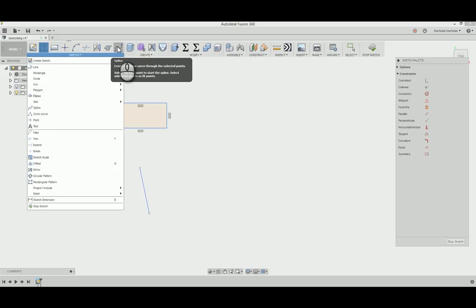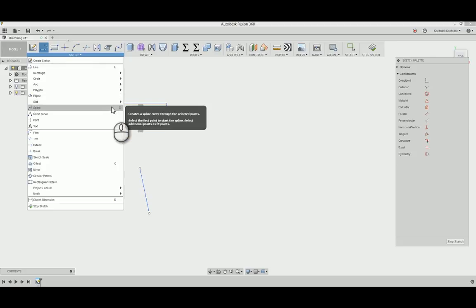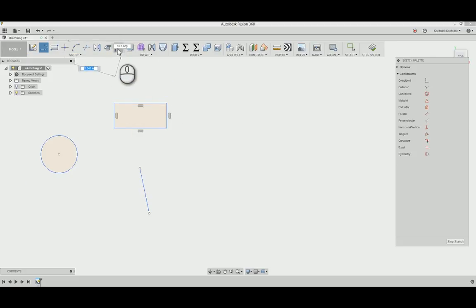My advice on best practice: only pin things that you can't quickly get from the keyboard. So don't pin line, don't pin circle, like the center point circle, or pin rectangle, because those you can hit on the keyboard. Just pin things that don't have a keyboard hotkey. Okay? So we're going to click the spline. I pinned it. And splines are really cool. I love them. Very curvy.